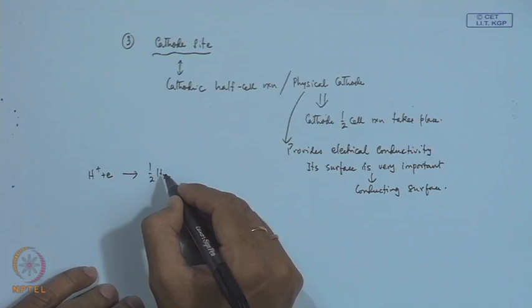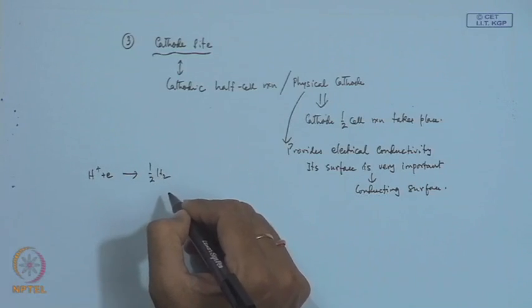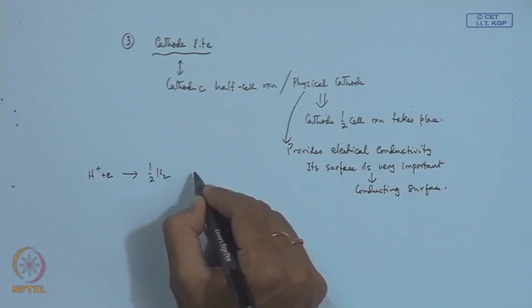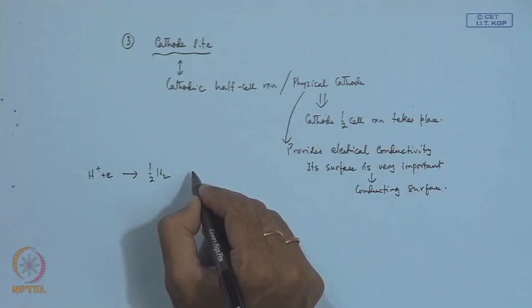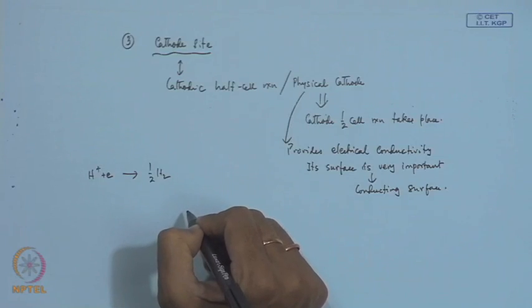And this distinction between cathode reaction and cathode material is important when we look into localized corrosion. Okay. Localized corrosion means the corrosion when the corrosion is very much localized in nature. Basically it may be thought that the regions which are not corroded may be cathodically protected.